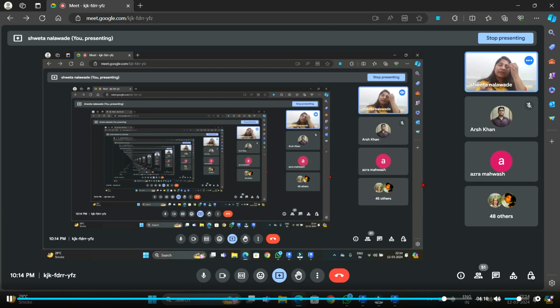2D lines are basically, if you create them on level 1, they would only be visible in level 1. But if you use a model line instead of a 2D annotation line and create it in level 1, it is not only going to be visible in level 1, but it will be visible in 3D as well. So it is like a reference in your 3D view as well. When to use what will be understood as you work around. But yes, you do have options of using the same lines in different perspectives and different ways. So it depends on your requirement.